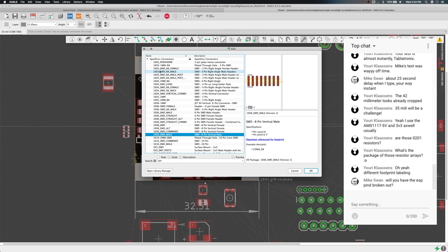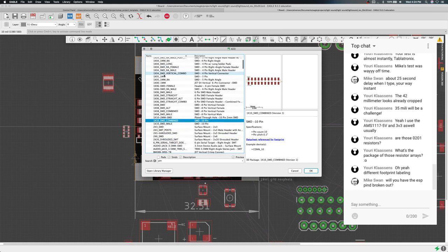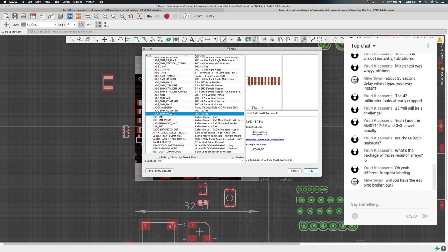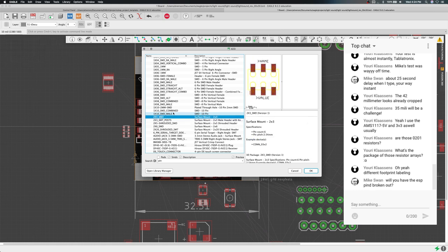No, yeah, something like that. Where you can put the flat SMD mount, and you can use either female or male sockets, and they'll just kind of come out the sides of the board, but they'll line up in the middle, so they won't actually stick out of the side of the board. And then you can put headers on there, or you can just solder to them.